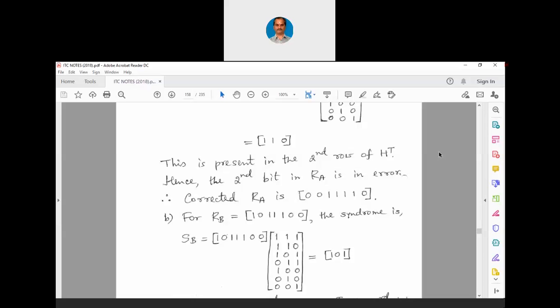Let me elaborate my question. For the very first bit error, first position's bit error, you should get a syndrome of 111. So my question is, the syndrome 111, is it predefined? Because you can see 111, 110, 101, 011, 100, 010, 001. Is it predefined is my question.